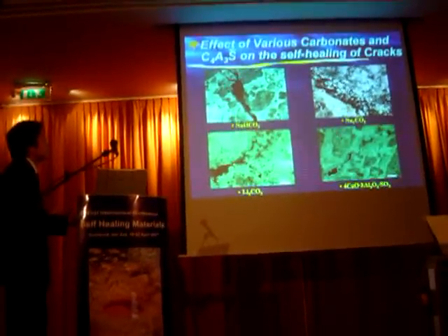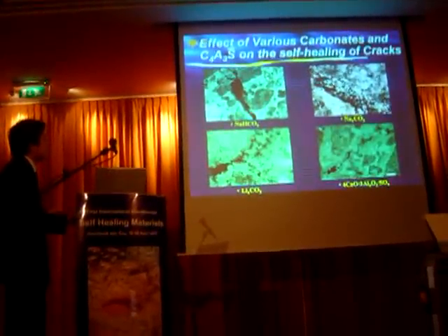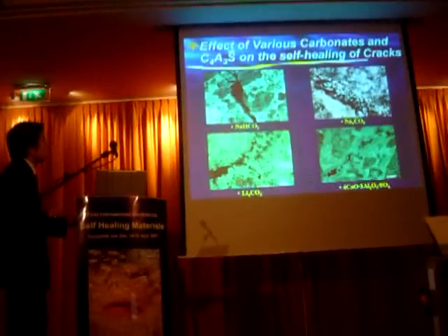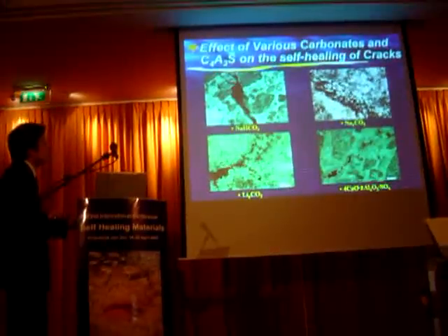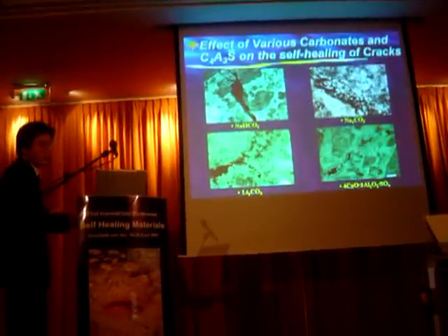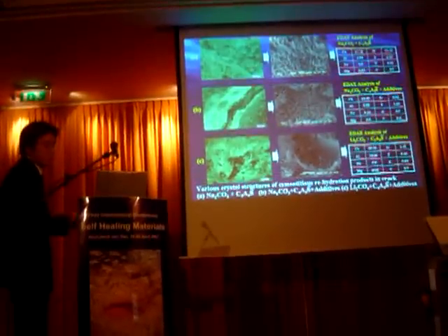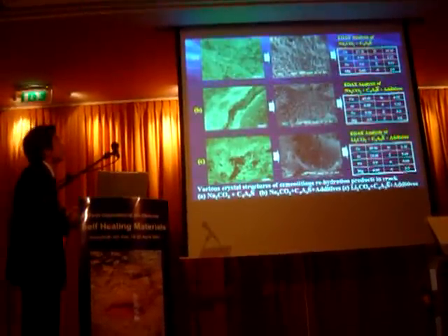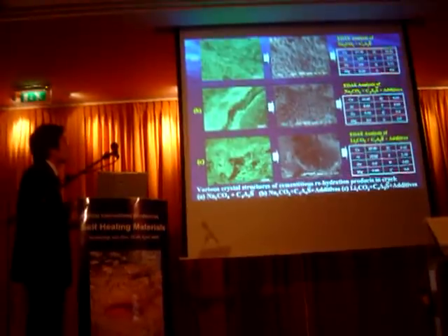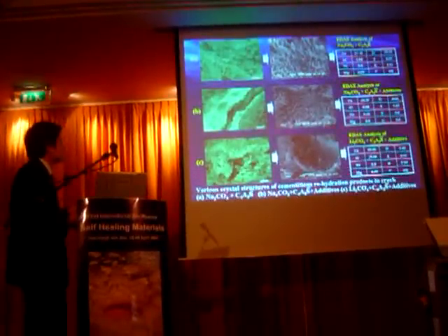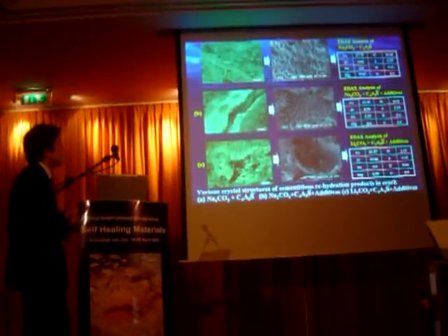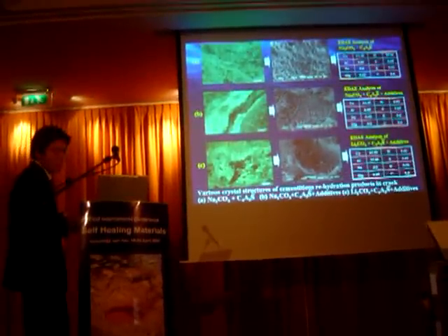In the case of sodium carbonate, lithium carbonate and calcium sulfoaluminate, you can see that there is cementitious recrystallization between the crack. And moreover, with the addition of calcium sulfoaluminate and some other mixtures, they show various crystal structures of the cementitious rehydration products in cracks, like this.